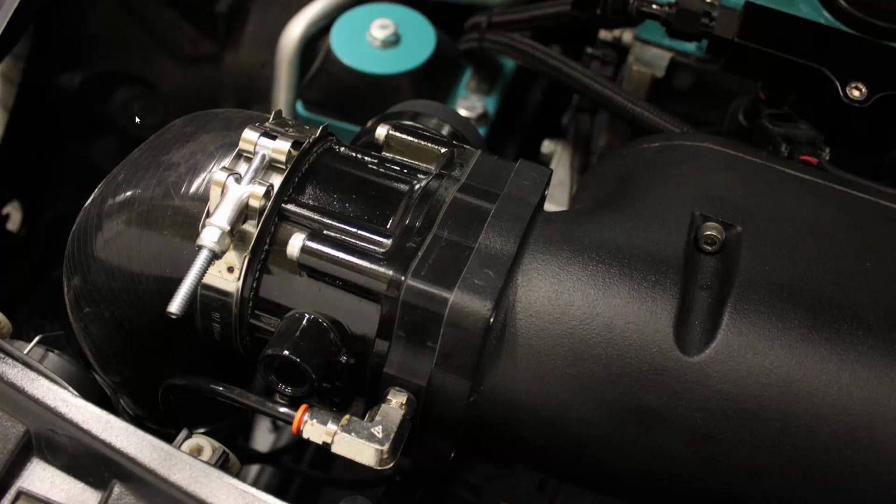So like I said, I did run this at idle, but I didn't go any farther than that. This is going to need further testing, and I'm not 100% certain how comfortable I am with how far I'm going to take it, but we'll see. The material itself, the Ultem material, withstands the temperatures no problem. I was going to shoot this with my laser thermometer. Totally forgot, but just judging by the temperature, the coolant runs about 90 C, so 190 degrees Fahrenheit, give or take 5 or 10 degrees. This area here is going to be less than that, but even if the Ultem was in contact with 190 degrees Fahrenheit, it would not be a problem. All right.